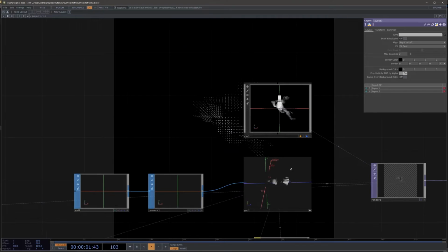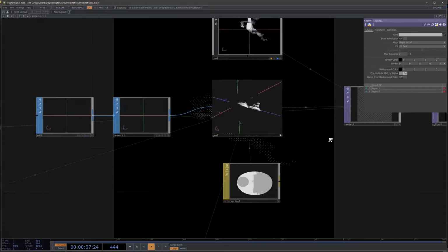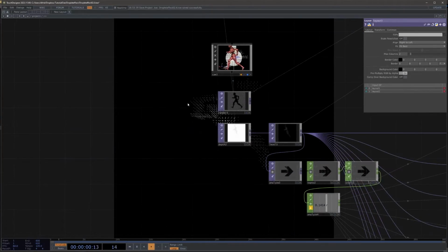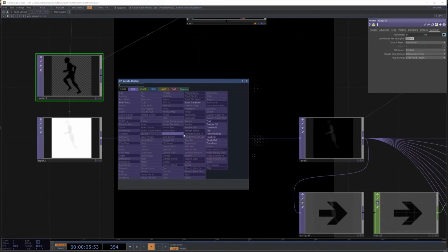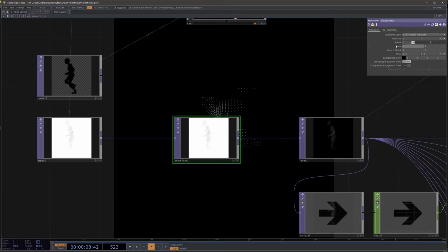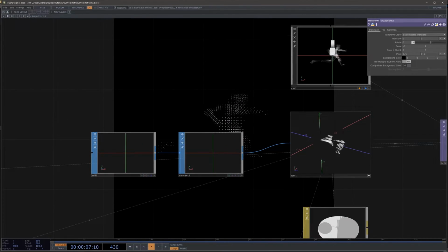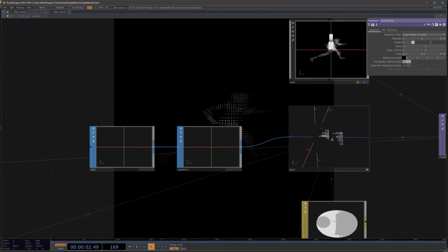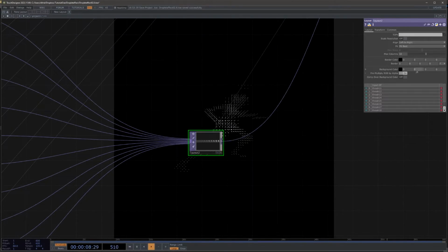And then still we have some issue. They are not well aligned, and this is because here we have to transform our render and turn the picture to the other side. So I'm going to add a transform, and in the transform scale I'm going to put -1. So now they are well synchronized with each other, but again we have an issue. This one should be on the other side, or it should be reversed. So I'm going to head to layout 2 and say from right to left.